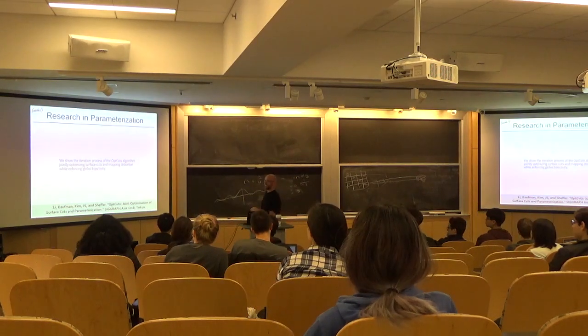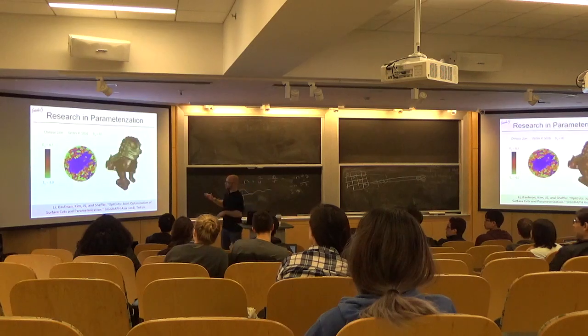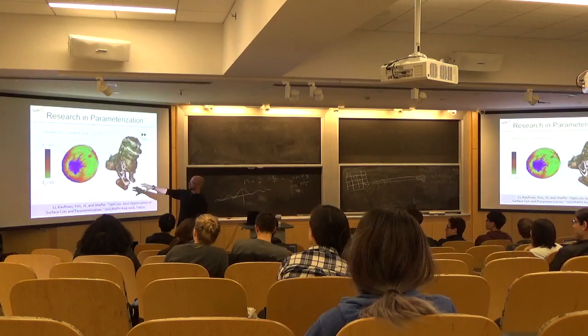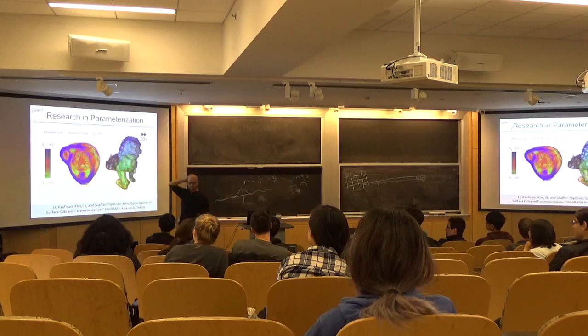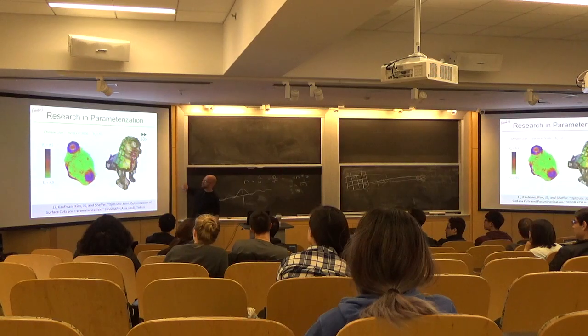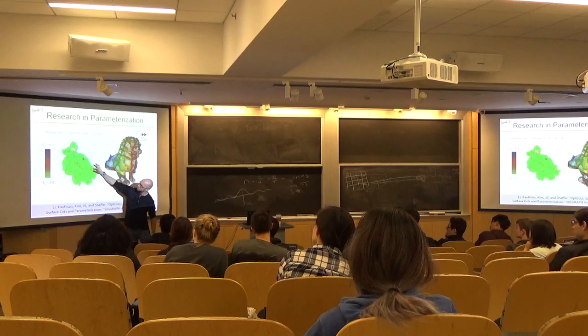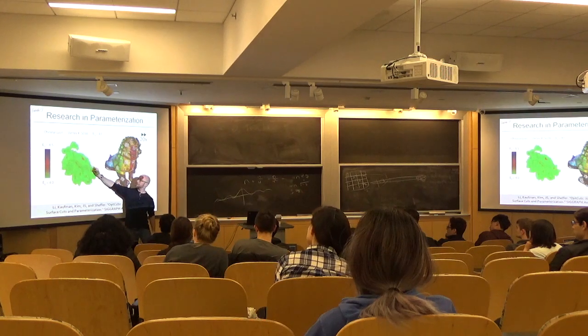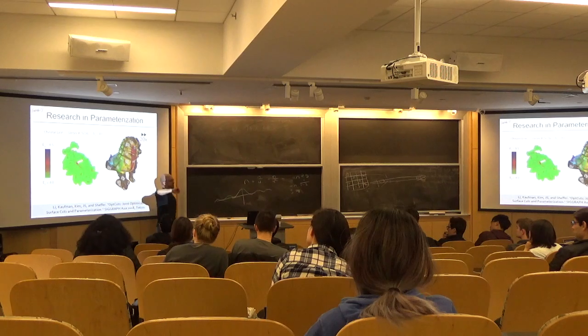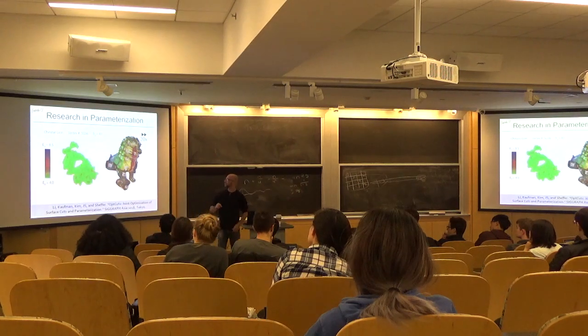I thought I'd share. Then I'll show you the basic contents of the class. So the tools for these kinds of problems look like what I'm showing you here. They come up with some terrible initial guess for the parameterization. And then what they're doing is taking scissors and cutting along the surface to reduce the distortion. And when two pieces are nearby each other, maybe it tries to glue them together and sees if that makes things bad or not. You can see that slowly over time it converges to a nice mapping of your mesh.